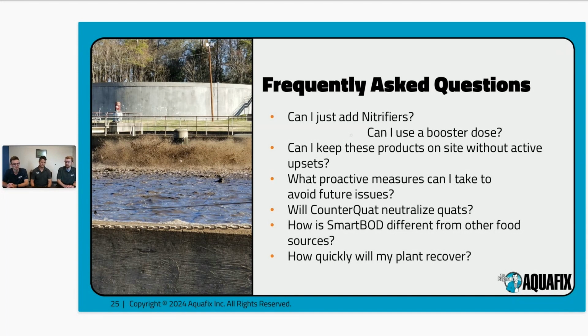Keep watching those other numbers that Tyler mentioned earlier: your ammonia, you see it start ticking up. You see BOD start ticking up. You start seeing settling start getting worse. Those are just more macro visuals of being proactive and noting when those change, because that means something is trending to an upset.